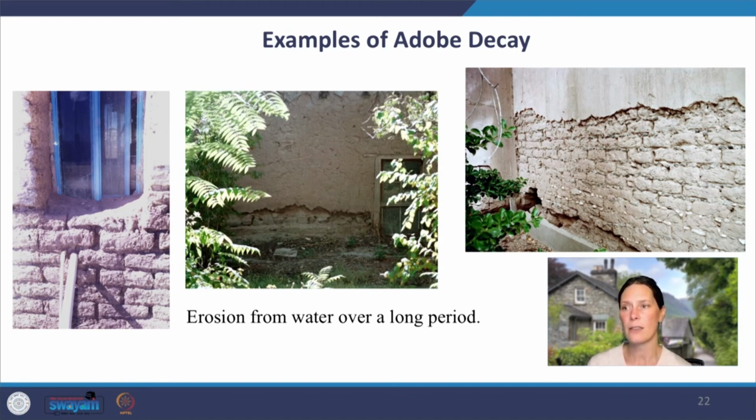In the stucco case, to the far right, you can see an area of brick at the bottom that's completely undermined. Because plasterwork is labor intensive and potentially costly today, many people want to take the seemingly easy and best option of applying concrete stucco rather than earthen or lime plaster. Because you can't see the slow erosion of the stucco, deeper damage occurs in the clay bricks. They will erode with the stucco, holding water, but they look generally fine.